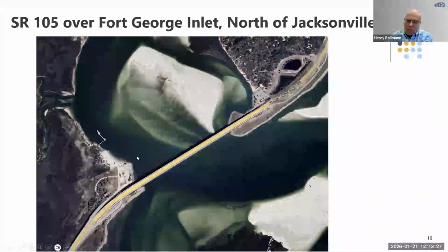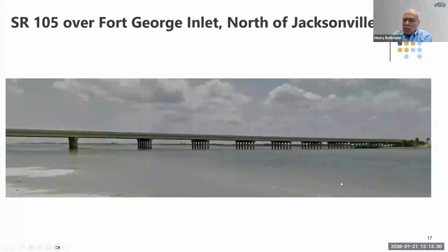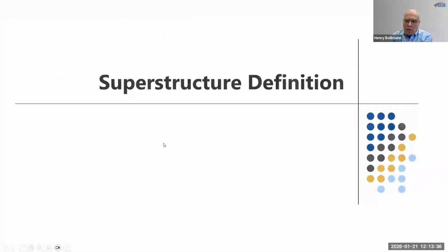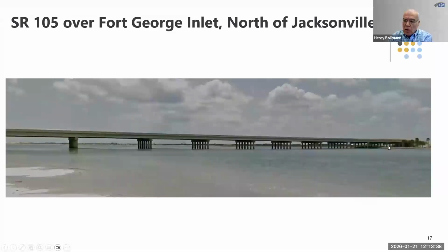And so this is another picture of that bridge. The deep water was over in this area, right in here. You can see back then, 25 years ago, we were already using plumb piles, vertical piles. I did away with using those batter piles. I hated them. They looked horrible.